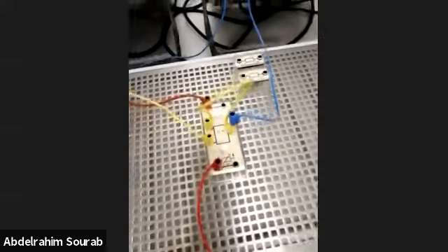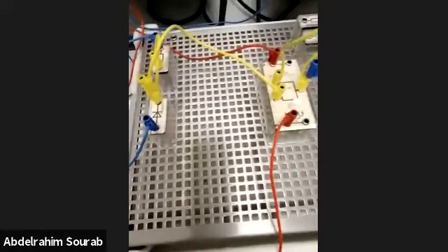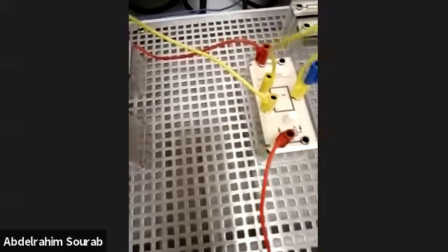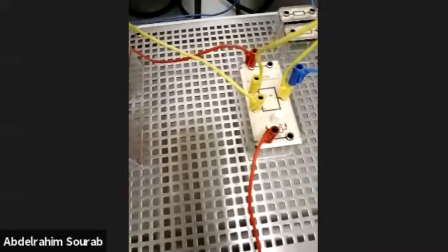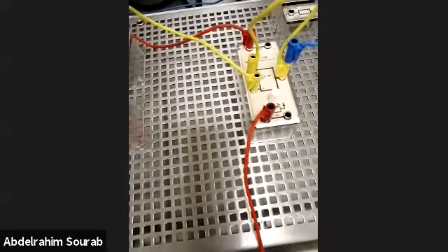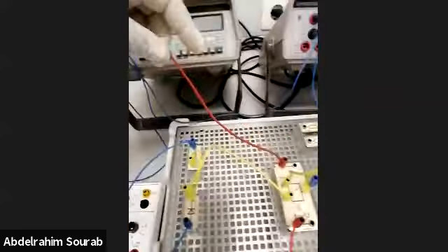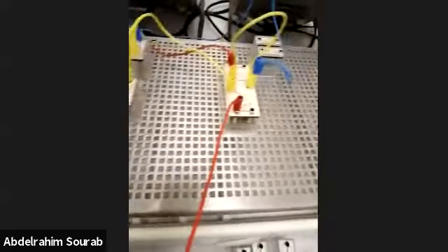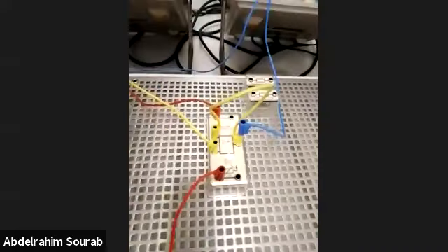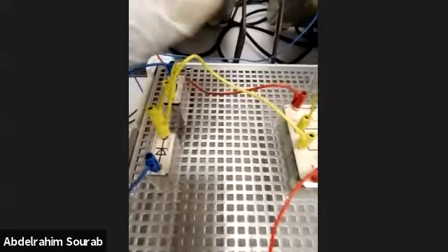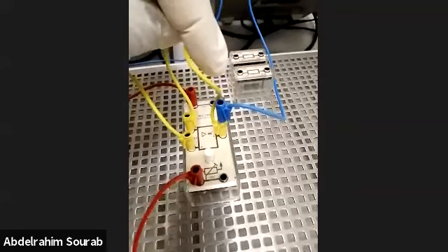Okay, so let us revise the connection quickly. We have, follow me in the circuit, we have minus 15 to here, to 1 kilo ohm. Then this connected to Zener diode, and from Zener diode to ground, and the op amp is plus 15 minus 15, and then from the cathode of the Zener diode directly to non-inverting input, and the inverting input is directly to output.